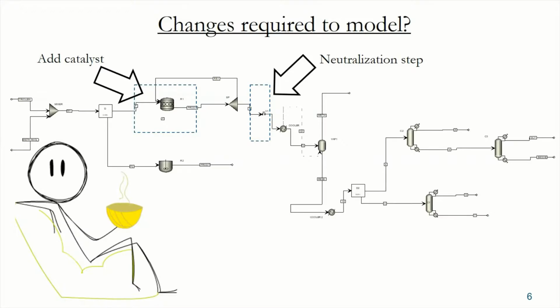Of course, the conventional and traditional way of producing biodiesel is simply to transesterify the oil, in this case the triglyceride, directly with an alcohol in the presence of an alkali or a base catalyst, right? However, this is only possible if the oil has low free fatty acid content, less than 0.5 weight%, and has no moisture in it, right? So it's water free, right?